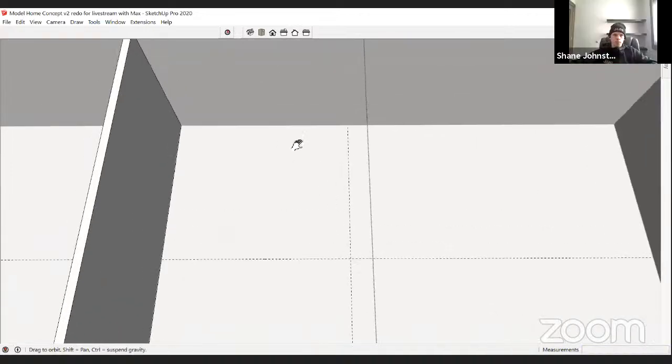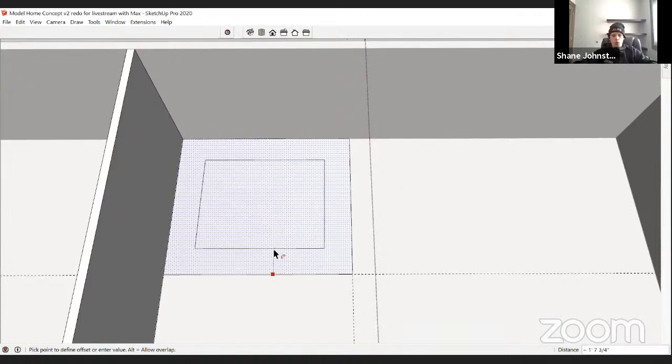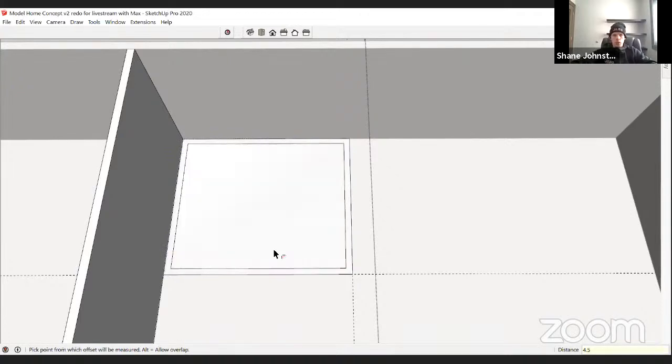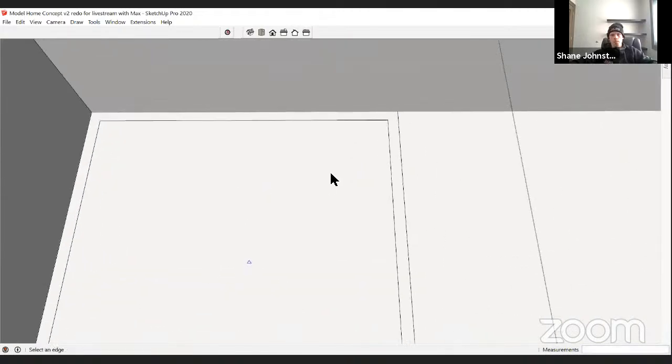Yeah, say typical exterior walls run 2x6 and your interiors 2x4. You need a thicker wall on the outside to get appropriate insulation in there.